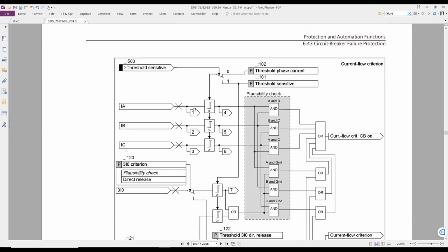Now, guys, we know that in the circuit breaker failure current mode, when I receive an initiation, I start to check whether the breaker is closed or open by measuring the current. So, which current is it? Well, all the options available in the relay, it would be the phase currents and the neutral current. But how? If we take, for example, the ABB REF 615, you can refer to its videos, and you'll find that in the ABB, you have three options: 1 out of 3, 1 out of 4, 2 out of 4. 1 out of 3 means that when initiation occurs, I check if the current of any one of the three phases exceeds the setting. This means the breaker failure activates and gives a trip.